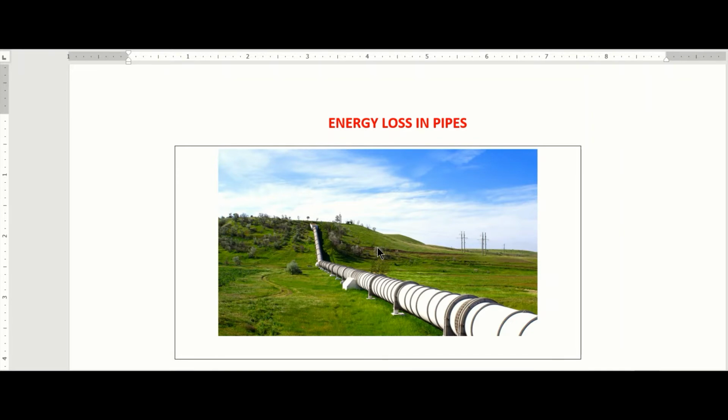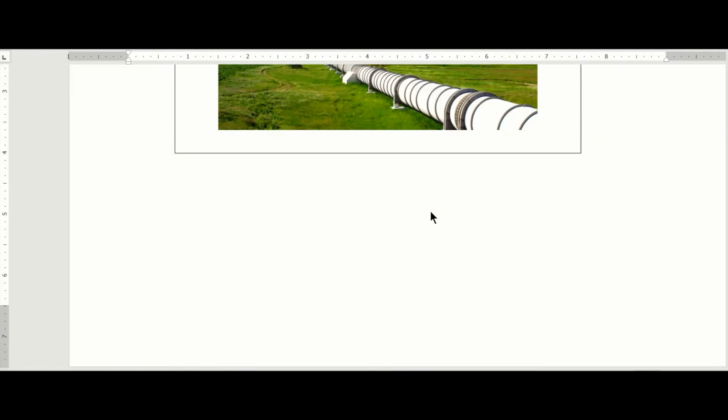Major losses in the pipe get accumulated over the length. However, major losses in pipeline can be brought down to a minimum by adhering to best design practices. If the pipe is long enough, the minor losses can usually be neglected as they are much smaller than the major losses.